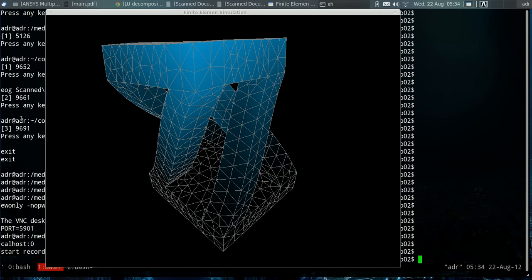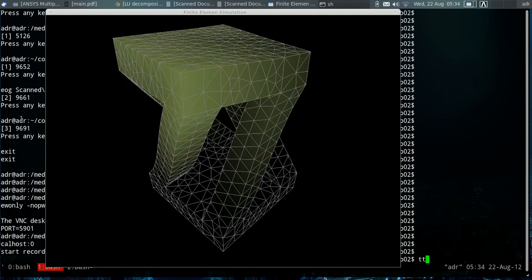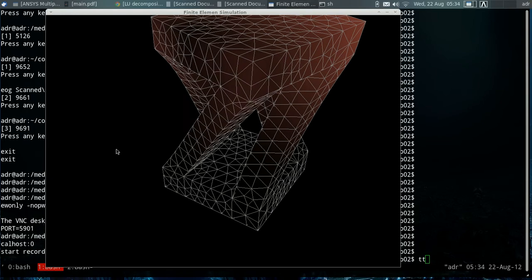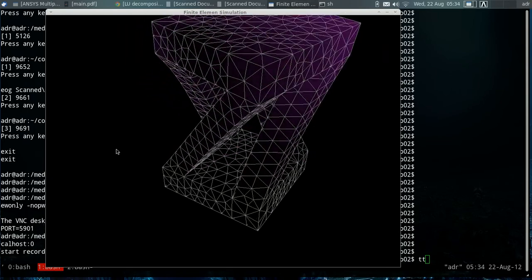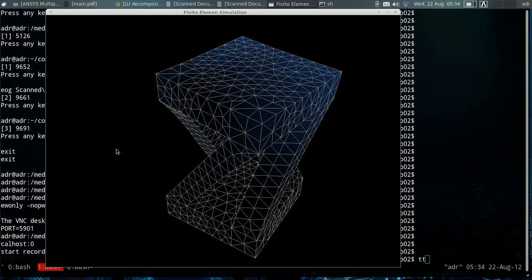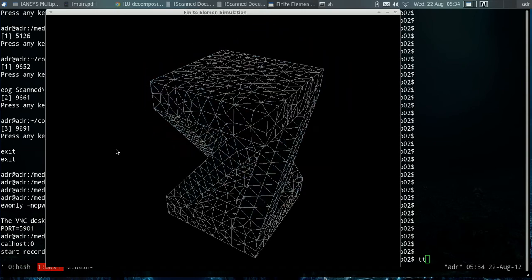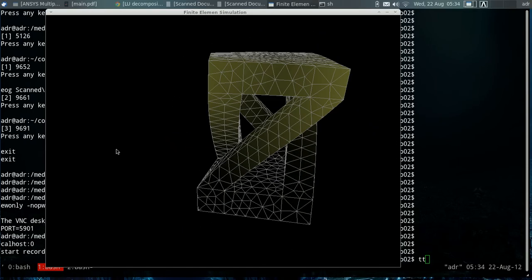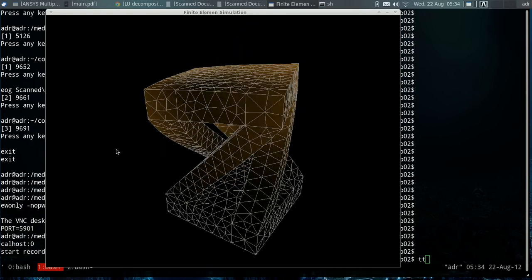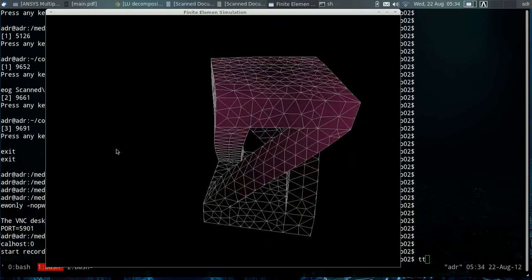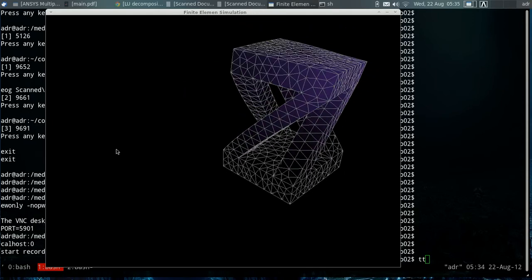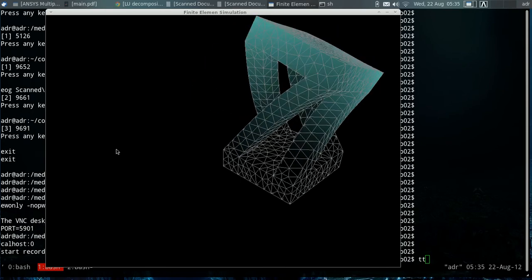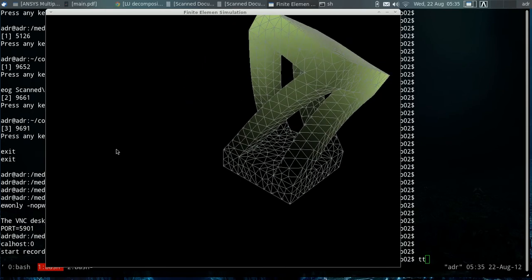I'm gonna show you this little program I recently made. As you can see, this program solves the displacement for this sculpture that is under some forces. It uses finite elements in shape of tetrahedrons, and basically, you can see the intensity of the color means the displacement of each node. The more color, the more displacement. And this displacement is scaled by a factor of 100.